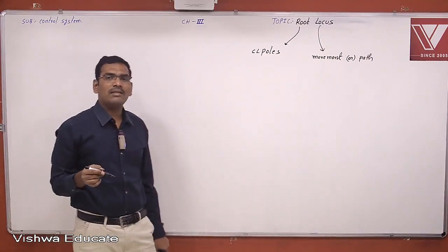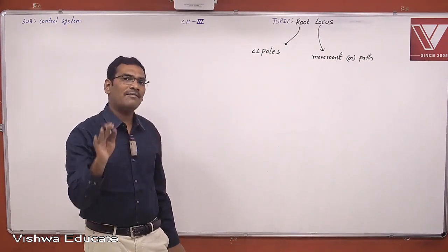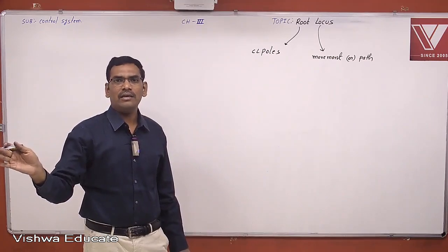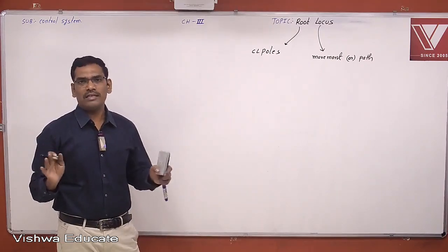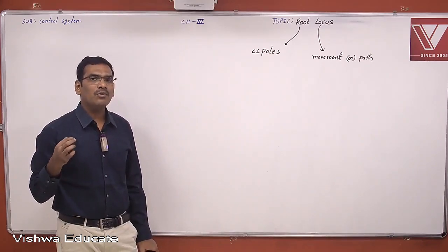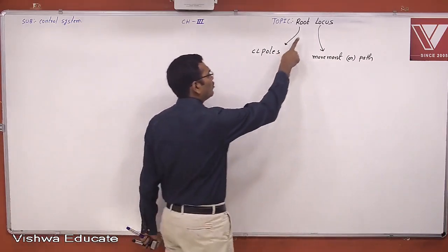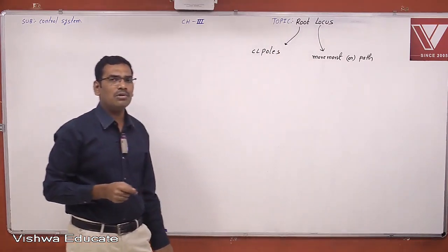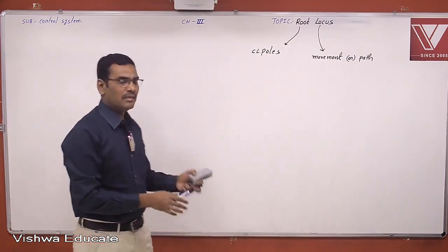With our basic knowledge, you know that the open loop pole is at one particular location, and its corresponding closed loop pole, after having a feedback, may be at a different location. Let us assume the open loop pole is at one location and the closed loop pole is at another. Those two locations are different because in a closed loop control system there is feedback. Because of that feedback, the closed loop pole location changes, but it is a fixed location. What the root locus is saying is how the closed loop poles are moving. That movement, that path, is the root locus.